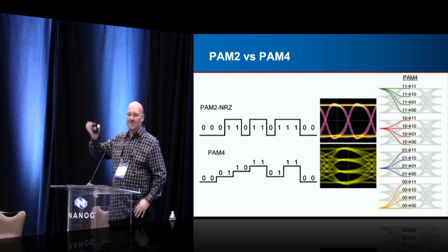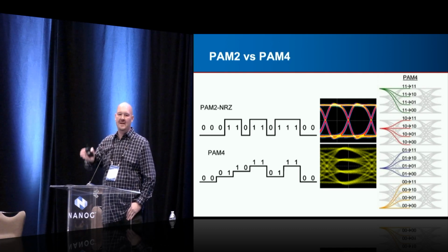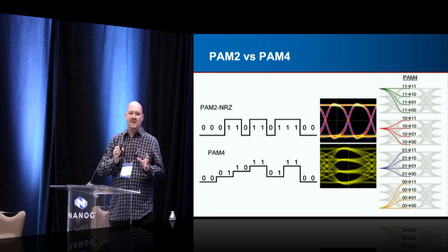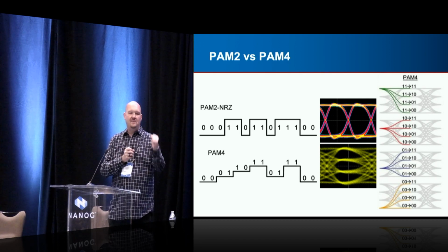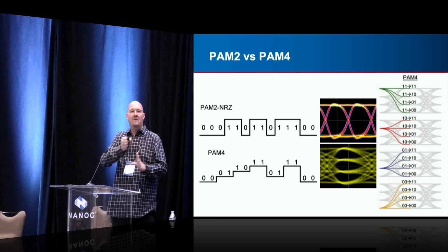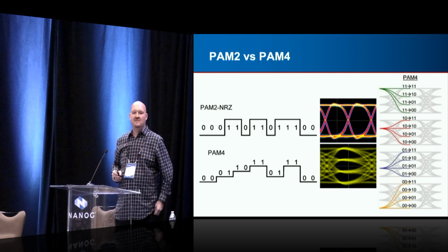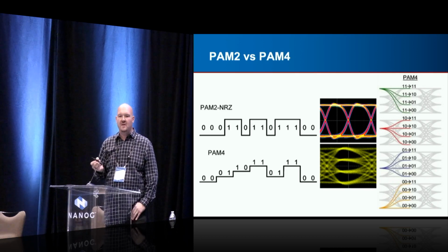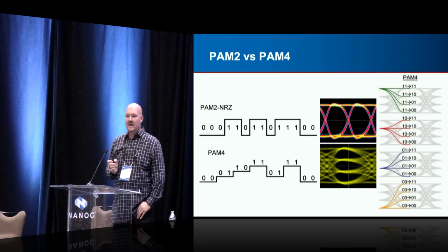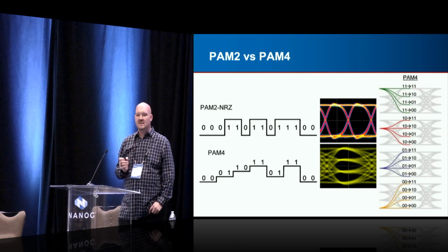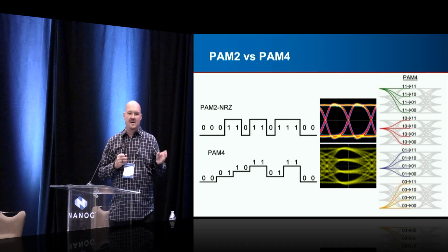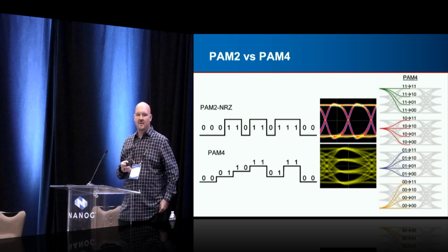You need a 100 native optical carrier. A lot of the 400 gig things are built around doing 50 gigabaud PAM4 and multiple channels of that. So PAM4 is very much tied to everything that we're doing in 400 gig client. And it's used in things like DWDM tuned QSFP28s done in PAM4 that you can carry over distance.